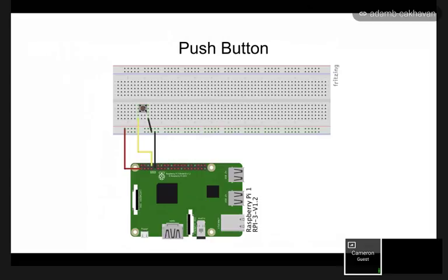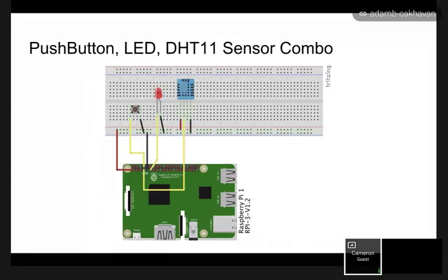And a push button, all it is, is a switch, right? So if we connect a little ground pin here to one side and then have the other side of the switch connected to an input on the Raspberry Pi, we could just say whenever the switch is not being pressed, don't allow electricity to flow through, and our data pin will not get any information. But when the push button is pressed, you do allow the flow of electrons, and then the data signal or the electricity will flow through the input pin and tell our Raspberry Pi, hey, this pin is lit up. I'm going to start doing some stuff that you programmed, signaling. Exactly. So you could cascade systems very easily.